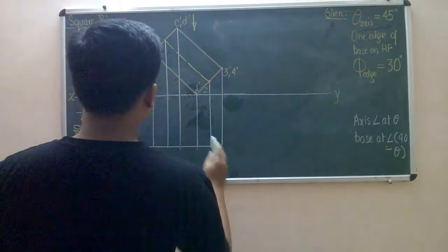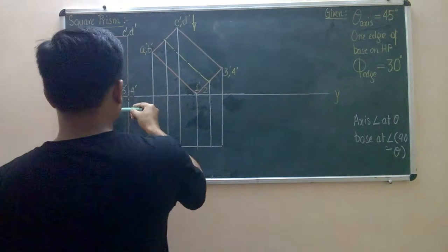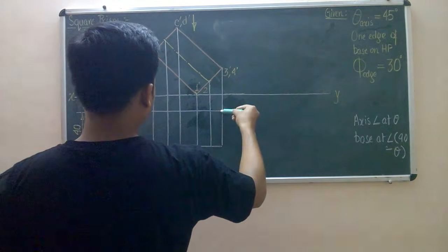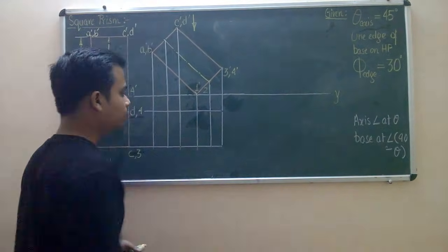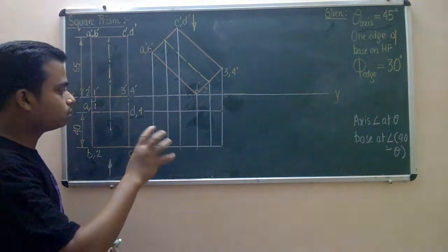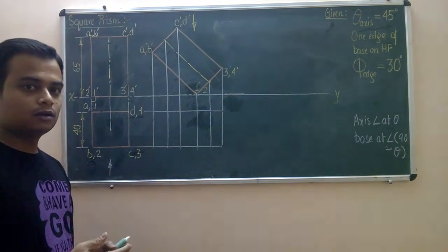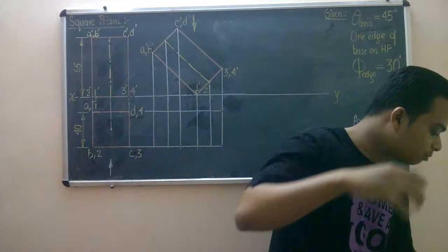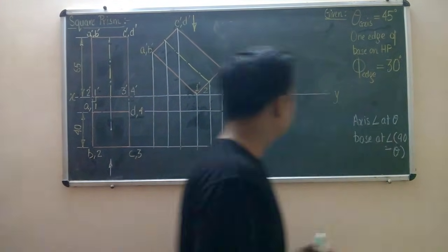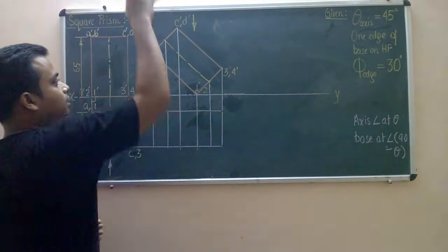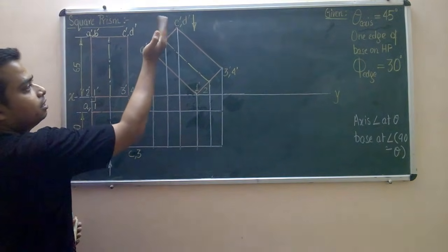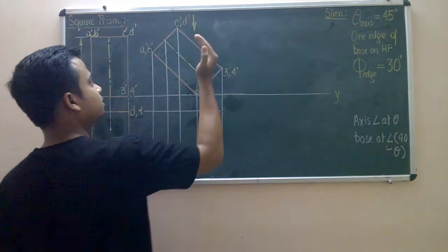So that's it. And let us draw the horizontal lines. Almost done. We're almost done, right? Now let us make those edges by solid lines which are absolutely evident from the top, which you can see directly. One thing is absolutely clear, that there will be a face above, that is the ABCD face. This particular face will be seen, and this particular rectangular face will be seen. Okay.